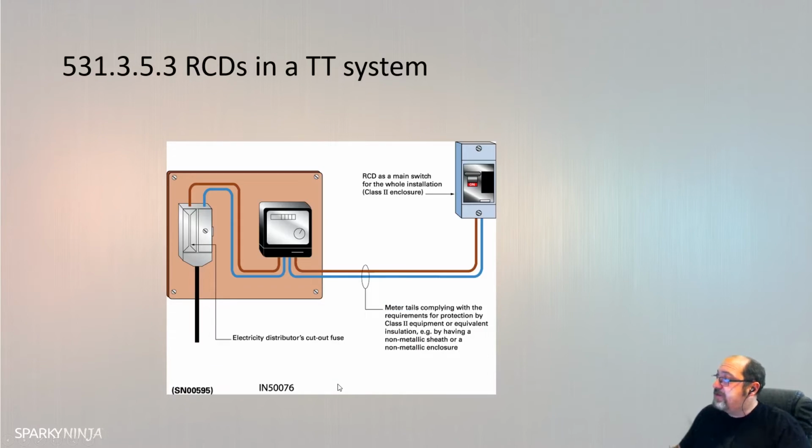With the TT system, at the origin of the part installation to be protected, and the requirements for unwanted tripping to 531.3.2 shall also be taken into account. Okay.